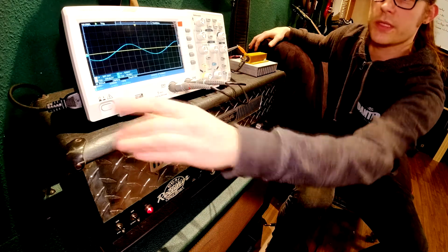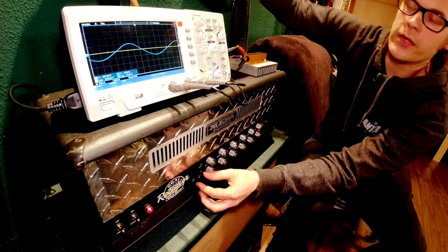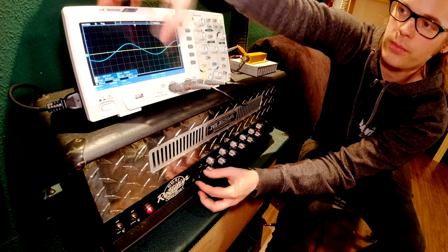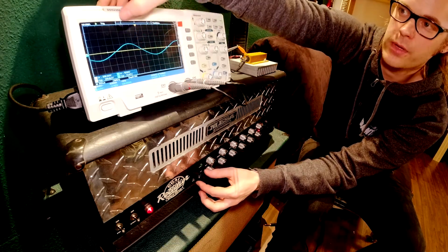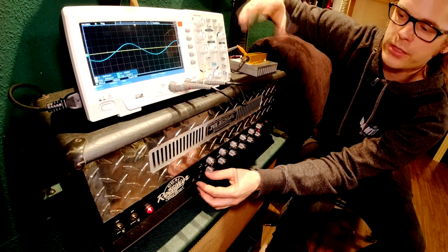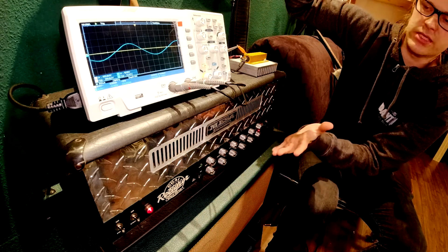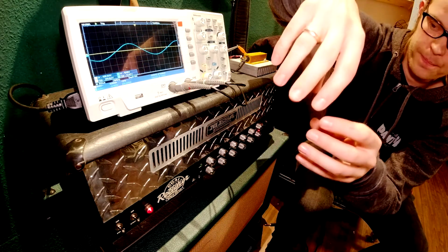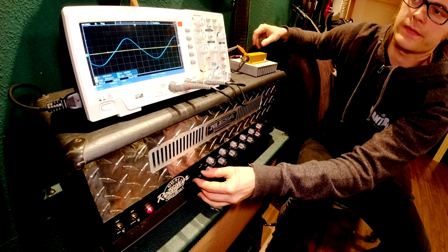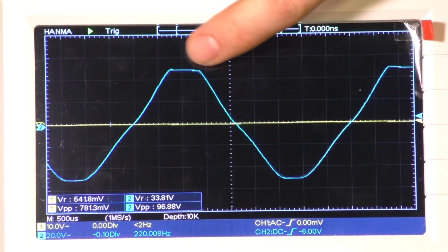Okay, I'm going down one step further in the divisions, and now we are looking for something that is distorting our sine wave, normally at the top or the bottom of the peak, because there is the point where the power amplifier is delivering no more voltage, so the power amplifier is getting into saturation because the power supply is not delivering more voltage. Okay, let's push that, and there is our top. Here we see it, and there it is down.